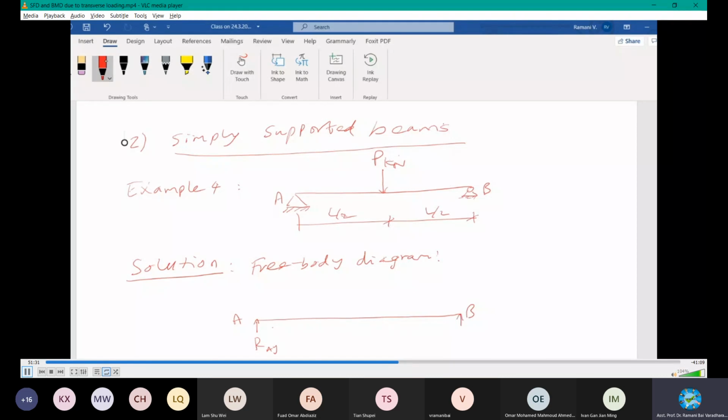And then also here, because it's again a hinge support, I will have a reaction at support B, RBY, in the direction of Y. And then the distances are L by 2, remain the same. Just mark here for our free body diagram. The free body diagram is the diagram with the load, reactions and the distances, right? All the given information. P kilonewton, right?